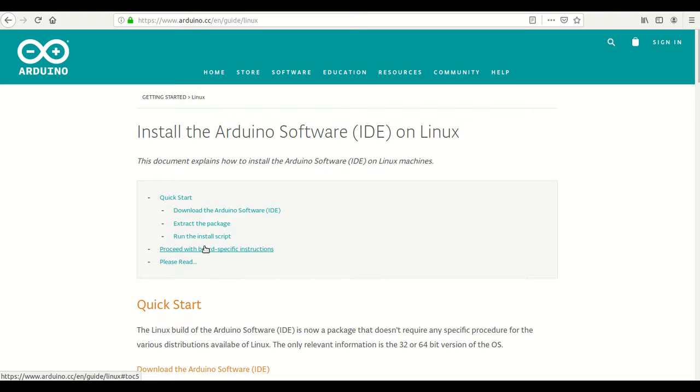I'm going to quickly show you a tutorial for how to set up your first Arduino sketch. A sketch is basically just a little routine, a piece of code that you can upload onto an Arduino and have it execute there. It's like an embedded piece of code on the board itself. In this case, I'll be using an Arduino Uno, and we'll be using the standard Arduino IDE for Linux, just because that's what I use, but I assume it's just as easy on other operating systems to get things set up.